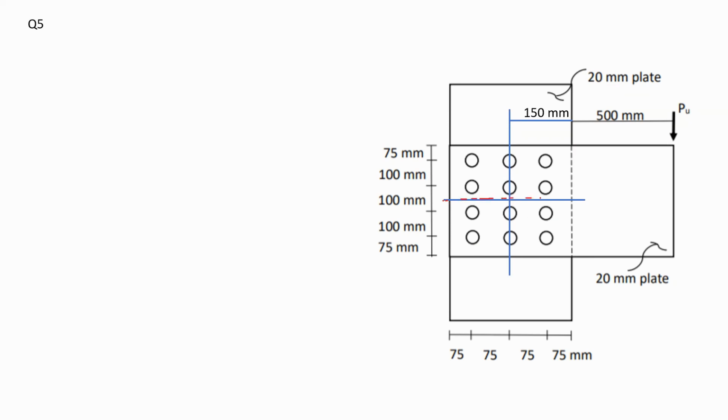In here, these 4 bolts, these 6 bolts, and the 6 bolts at the bottom, it would be in between. That's my x-axis. And the y-axis would fall in the middle right here. I don't know how to really explain this because it's very logical and very obvious. But anyway, that's the centroid of the whole group of bolts.